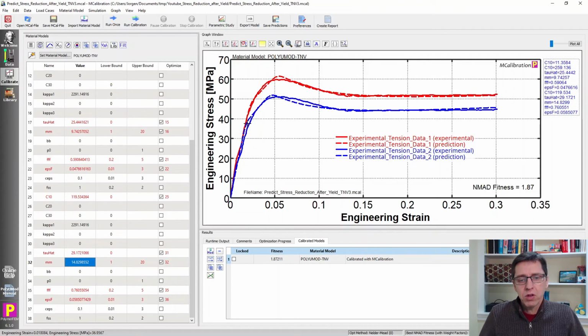And because of this way of thinking about it, it's pretty clear that three networks is usually enough to capture the response as accurately as one needs. You could go to a four-network model for this, but I have very rarely seen the need to do that, so I wouldn't recommend it. It's harder to work with a four-network model than a three-network. So that's why I typically recommend for thermoplastics, three networks is what you need in order to get good accuracy, but don't worry about going more than that for basic viscoplastic materials like thermoplastics.